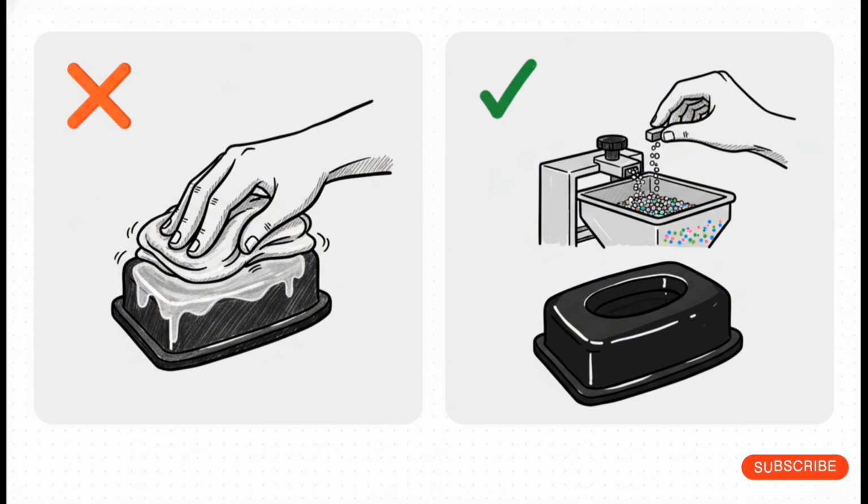This slide shows you exactly what I mean in the real world. Over on the left, you see the common mistakes: trying to reduce the pigment to hide black specks, polishing a part with blooming, or changing the whole color to hide streaks. And on the right, the correct approach: find the source of the contamination, fix the additive dosage, and fix the mixing process. You have to fix the cause, not just cover up the symptom.